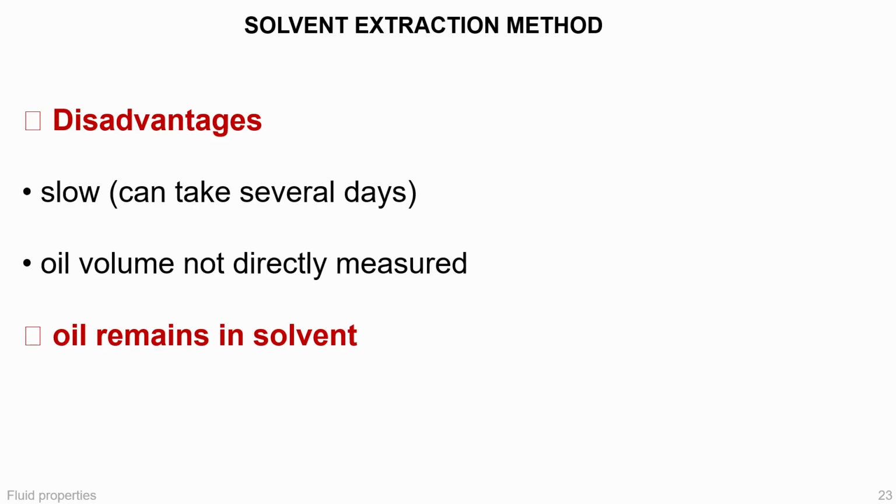The disadvantages are that it is slow, it can take days, and oil volume is not measured directly because oil remains in the solvent mixture. So solvent extraction is higher quality for some outcomes but slower and requires careful handling in calculation.